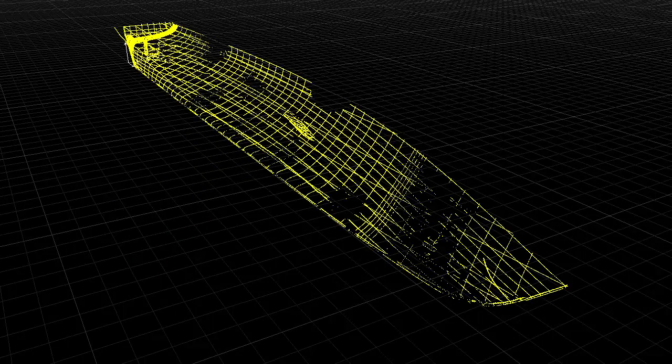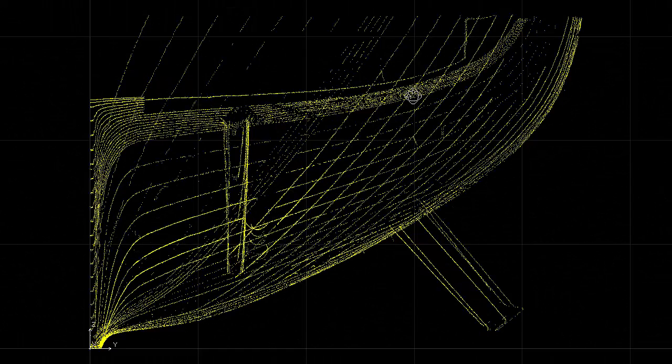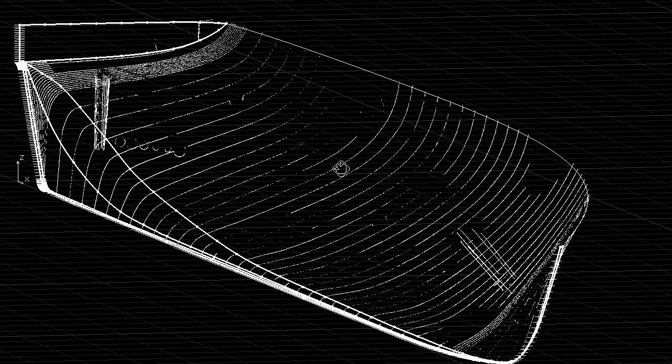We'll move on to just work with the sections. So now pretty much we can have a body plan. And using the body plan, just as a visual view, we'll start to make up the hull surface itself. At this point I'll bring in the boundary curves, because these take a bit of time to generate. It's quite challenging to find some of the features, particularly in this model, that make the best shape. So it was quite a few hours to make these curves, but you'll see now that once I've got those curves in place, generating the hull form is quite a quick activity.